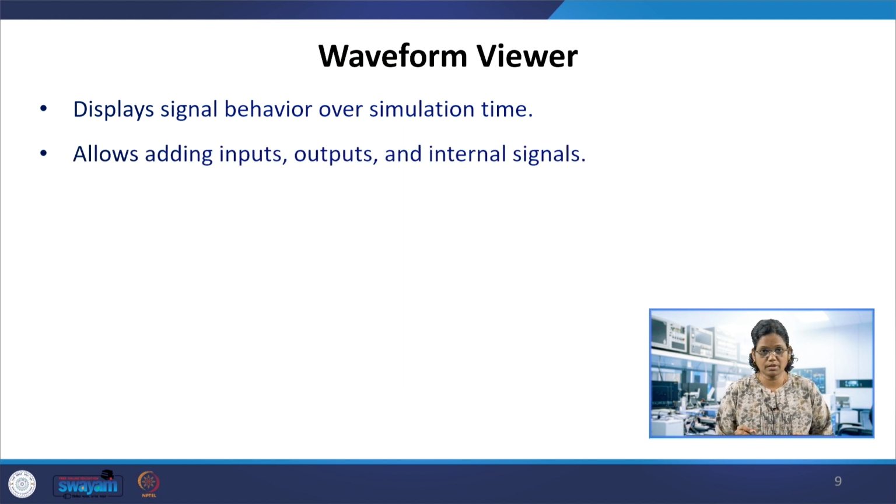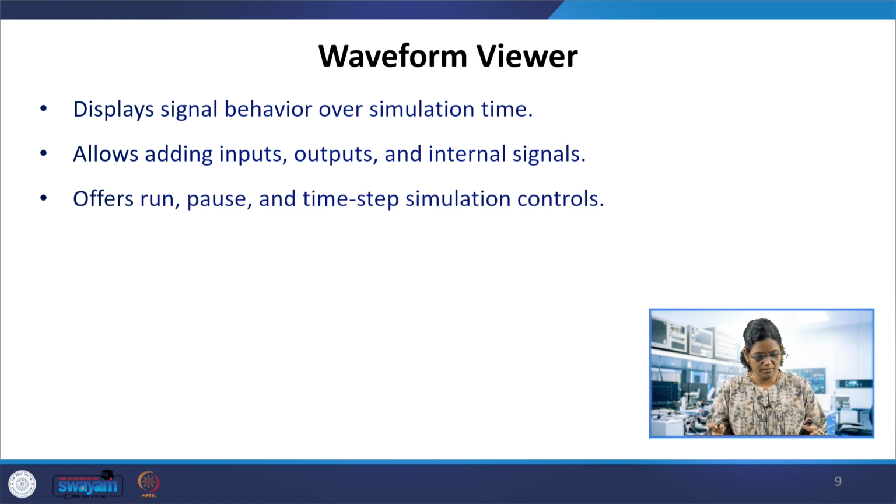It allows adding inputs, outputs, and internal signals. If we have a larger design, the internal signals which are defined can also be viewed using the waveform viewer. It's not only inputs and outputs; you can add other internal signals for viewing as well. This allows inputs, outputs, and internal signals to be viewed for changes over the simulation time throughout. You can run it and pause wherever needed, and time step simulation controls are available.